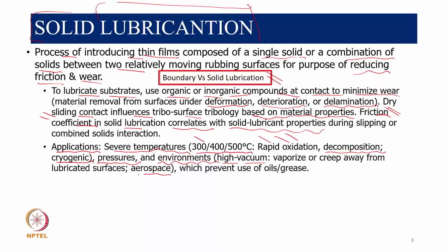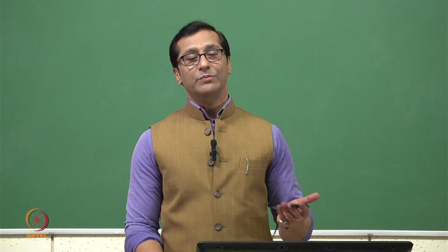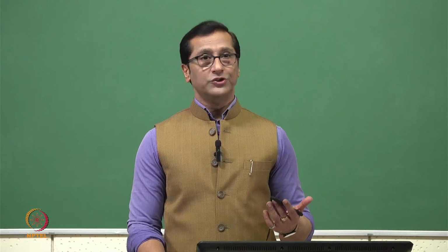Similarly, in aerospace applications we can't use a liquid lubricant, so we use a solid lubricant. So these are the conditions which prevent the use of oil and grease. Wherever oils cannot be used, or grease cannot be used, we should preferably go for solid lubrication.